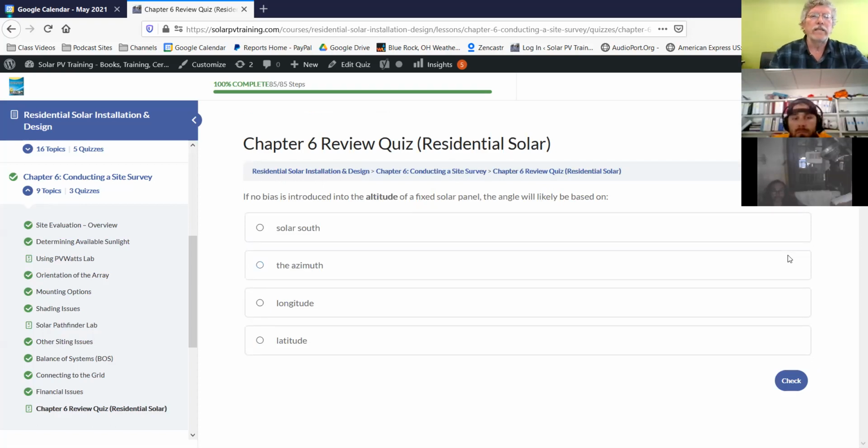So passive air cooling is typical, although now we're starting to see what they call floating photovoltaic solar arrays. They sit on the water, and that helps to cool. So you're seeing solar arrays installed in lakes, usually where there's hydro power systems. And that added cooling nature of the water actually produces more power, because the colder it is, the better the system behaves.